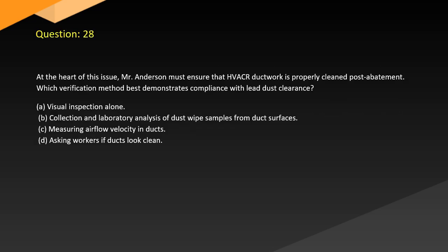Question 28. At the heart of this issue, Mr. Anderson must ensure that HVACR ductwork is properly cleaned post-abatement. Which verification method best demonstrates compliance with lead dust clearance? A. Visual inspection alone. B. Collection and laboratory analysis of dust wipe samples from duct surfaces. C. Measuring airflow velocity in ducts. D. Asking workers if ducts look clean.